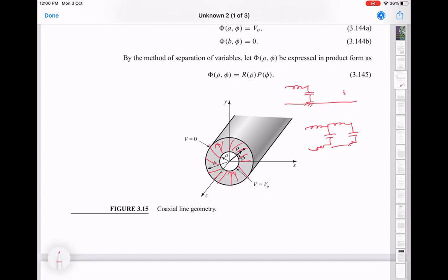Usually in any regular coaxial cable, there will be some dielectric, because you can't have an inside conductor just floating in free space. However, for smaller sections, like connectors, I was telling you on Friday that connectors are also small sections of transmission line, but of a different geometry and created in such a way that they can adapt a smaller cable transmission line to a bigger diameter, because those are easier to work with.